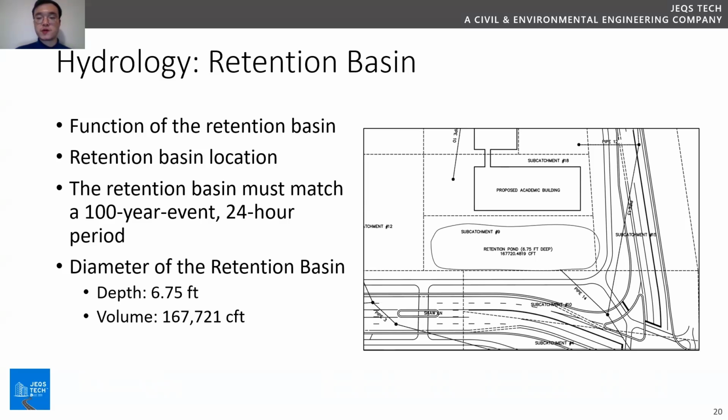The retention basin uses the traditional approach to hold the water and reduce the flow of the runoff by natural evaporation and infiltration. The calculation for the volume of the retention basin used geometric calculation and design, which includes the depth, length, and width. Also, the overall flow capacity needs to be determined first in the storm pipe system to design a suitable size for the water capacity of the retention basin.